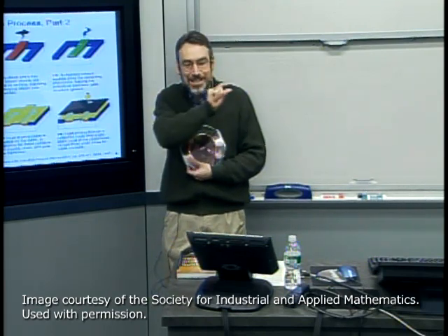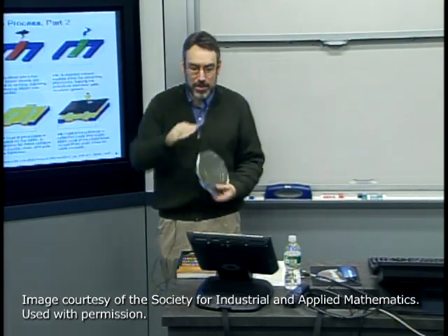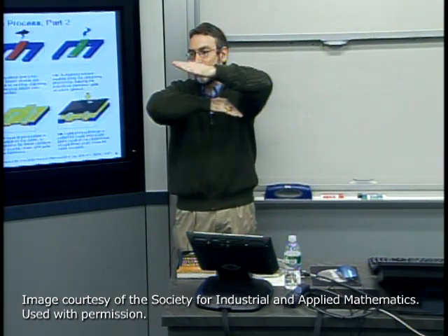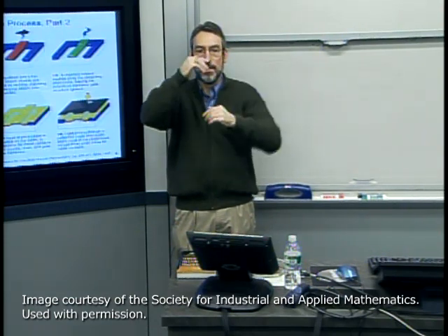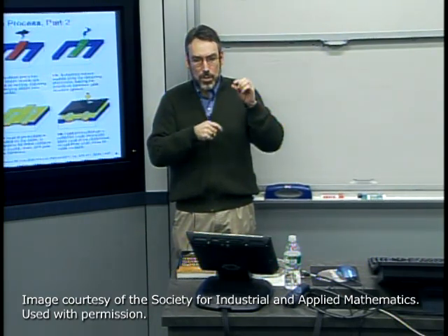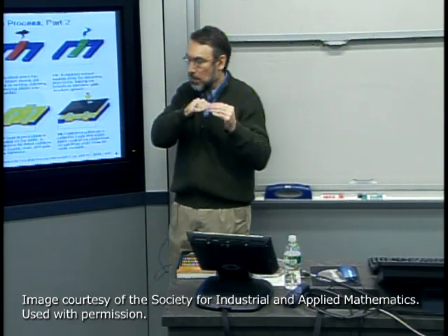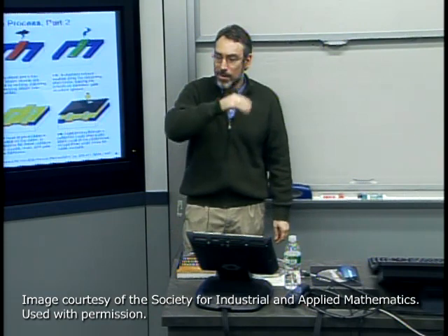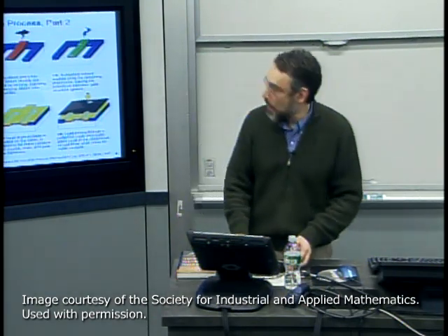They're imaging slices of that so that they can do all kinds of other on-the-fly alignment control as well as leveling, because it turns out the depth of focus is a big constraint. And if I have a focal plane mismatch where I'm in focus on the left side of the chip and not on the right, then I don't get the dimensional control I need. So it's really amazing innovations that are exactly driven by the manufacturing control necessary.